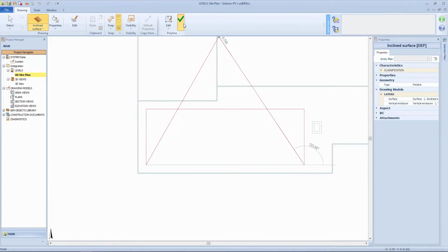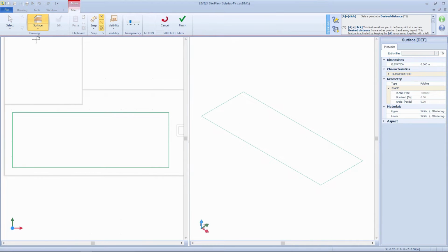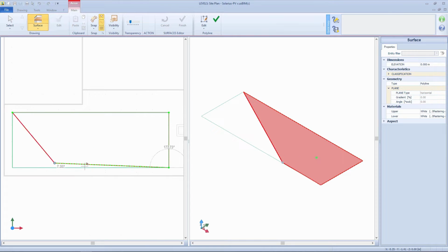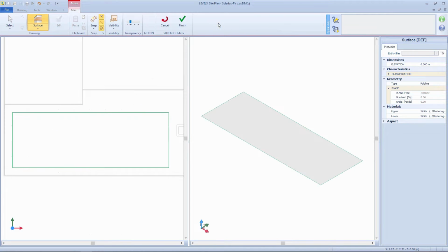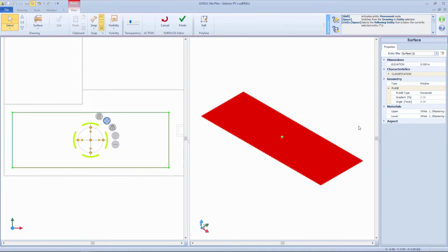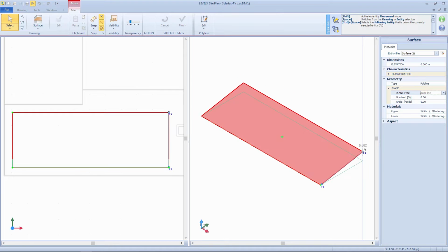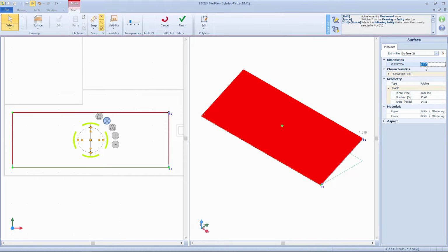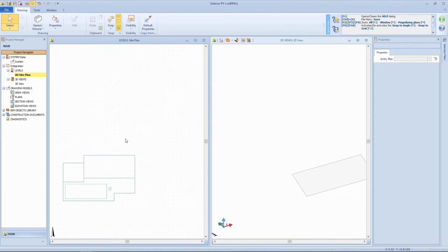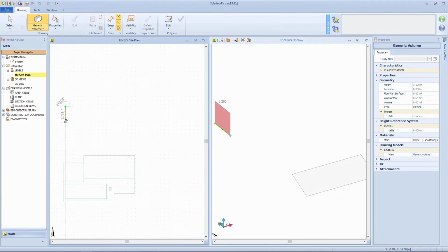Enter the dedicated editor, select the horizontal surface, and outline a simple perimeter. Switching from horizontal to sloped activates a plane inclination arrow for adjusting the elevation nodes. You can either move the slope node manually or insert a precise value of elevation. For instance, set an elevation of 1.5 meters, corresponding roughly to an angle of 42 degrees.